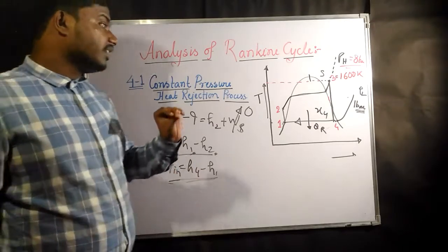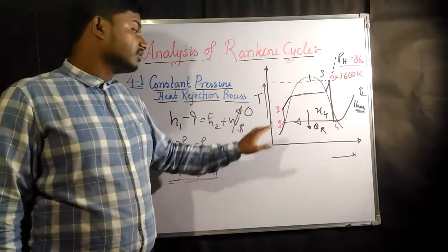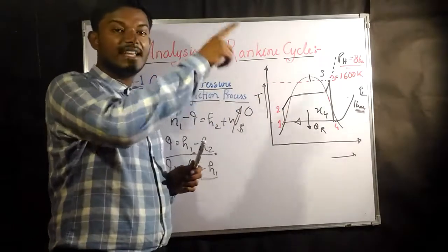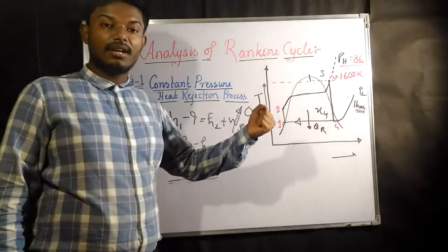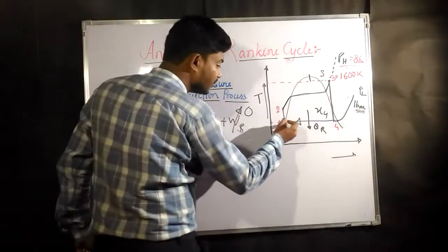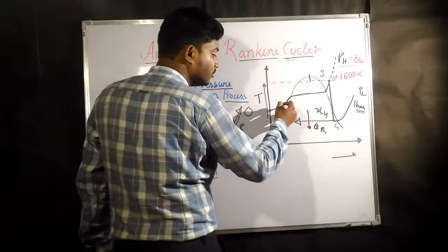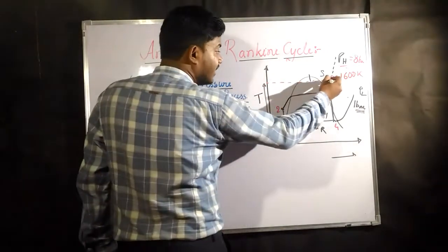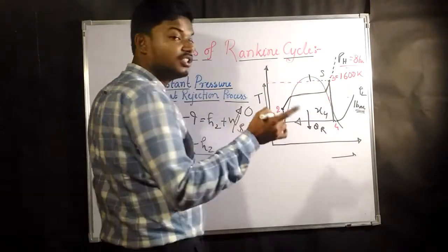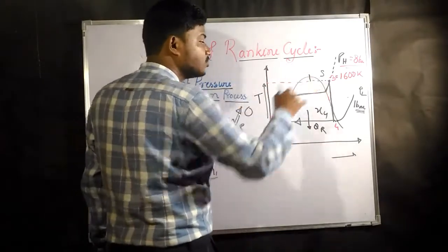Now if you see, we are constantly doing something: after finding the enthalpy in the process 1 to 2, it is like a chain. Without finding the enthalpy at one point, you cannot go to the next process. If you remember, from the process 1 to 2 we found H2. In the process 2 to 3, once we found H2, and from the steam table we got these 3, the enthalpy found in the first analysis helped us in the next process 2 to 3.